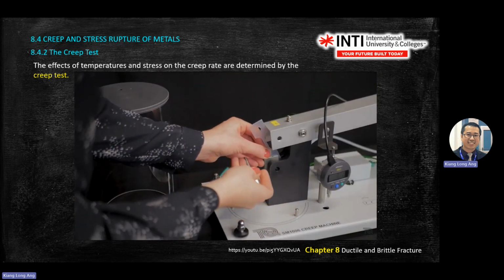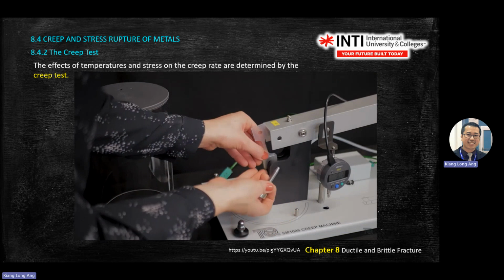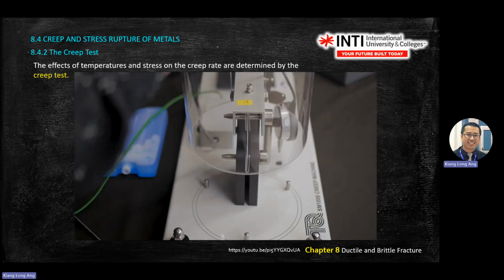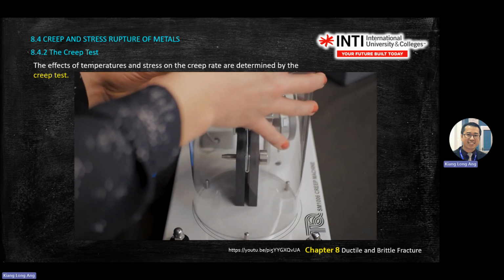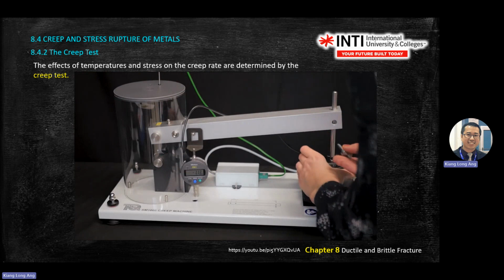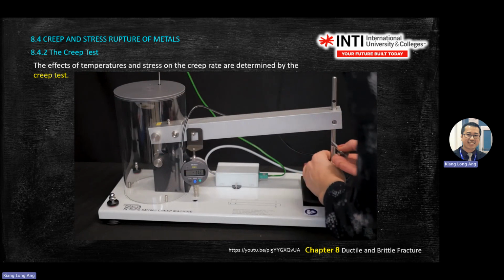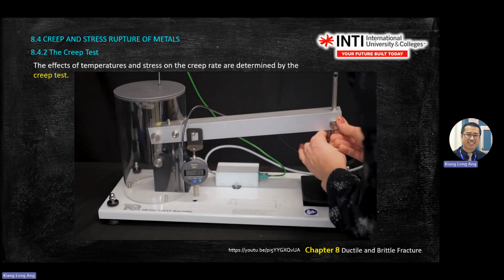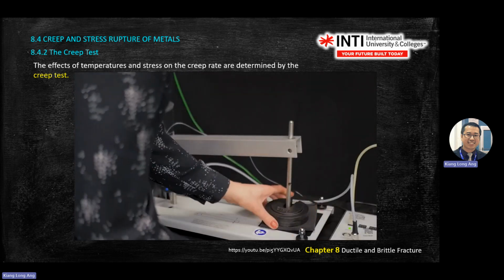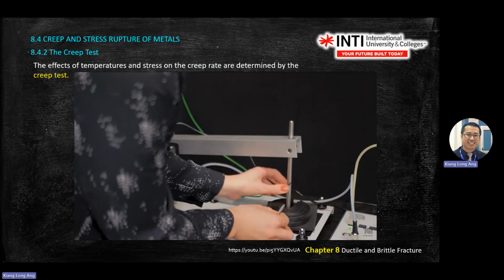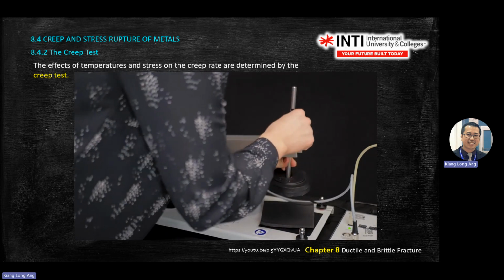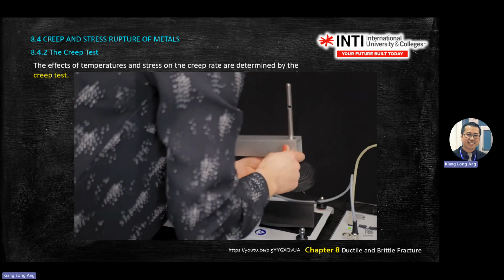Set up like this, we put one specimen in. Let's start with polypropylene, fixing it in place, and then you put the clear enclosure on over the top. Wait 5 minutes for the temperatures to stabilise and then record the temperature. Now it's time to start applying the load with the weights and recording the weights, giving the time between applying loads before recording the results, as shown in the user guide, to allow creep to occur. It's then a matter of taking recordings every 30 seconds.